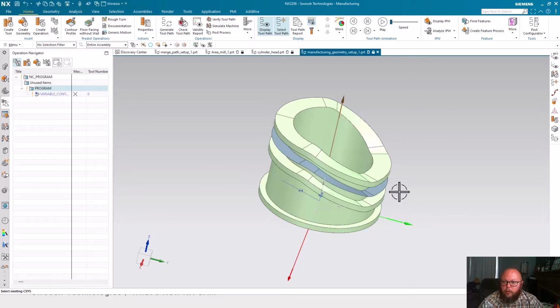By the same token, you could be working on a prismatic part and have some local shifts, and this will enable the code to be a little bit easier to read. So if I had some geometry on a side of my part, I could offset locally to the center of a face or a center of a bore feature that maybe things are dimensioned off of, generate my code. The G68.2 would offset to that location along with the rotary changes, and then my code would be based off of that local shift. So different strategies. You have the ability to operate the way you want here inside of NX.